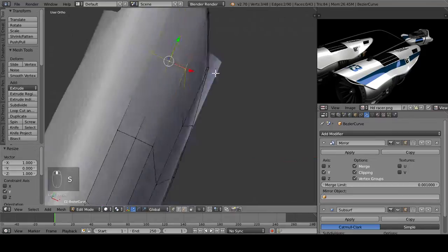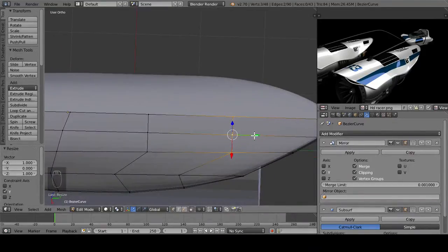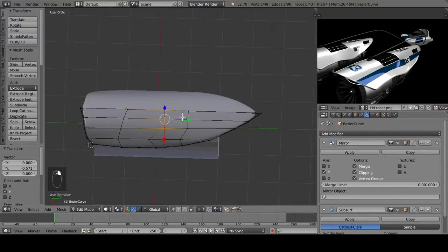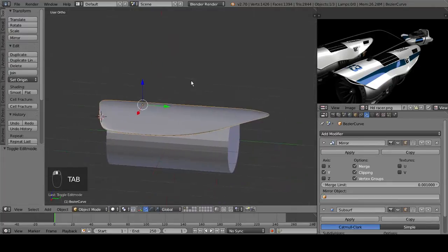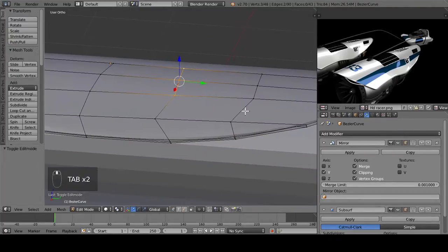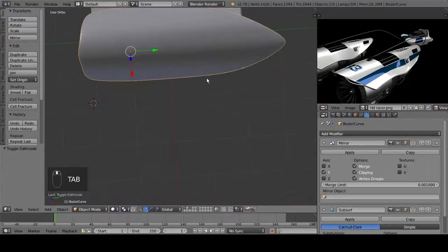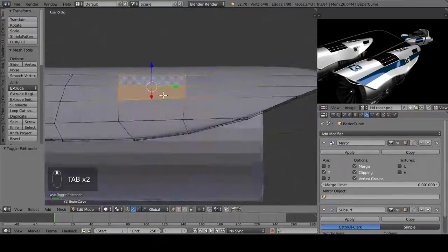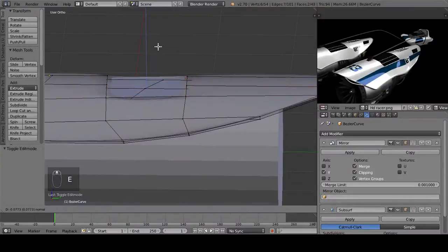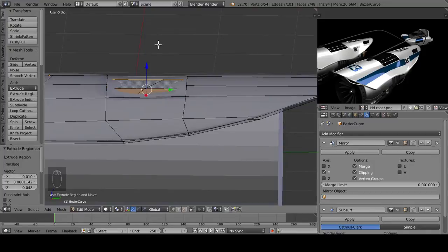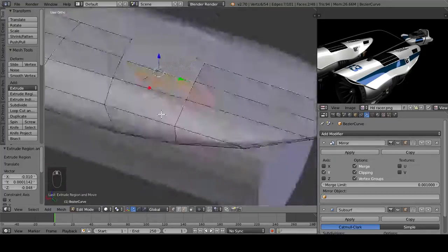Now these are straight. And I don't think I want the vents quite that long, so I'm just going to move it in some on the y-axis. Here we go. And also we want to keep all of our geometry lining up here, so I'm going to move it all down 1 so that it can stay nice and flat. Now we just extrude inwards, and we're immediately having an issue with breaking through